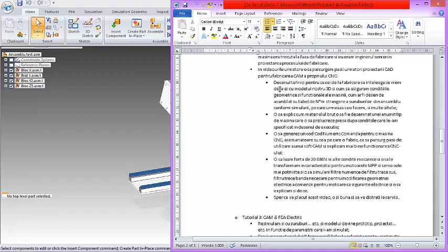So we are going to go through drafting for assemblies and parts so that the people from manufacturing can understand what we want with our 3D model. And we're going to follow the geometric conditions for the machine to work properly. We're going to do assembly drafting with specification of torque per screw in assembling the screws into the assembly.